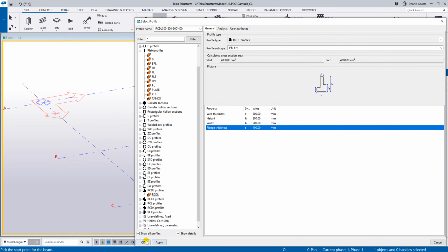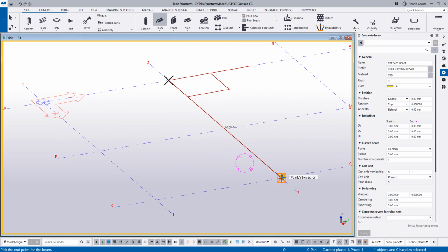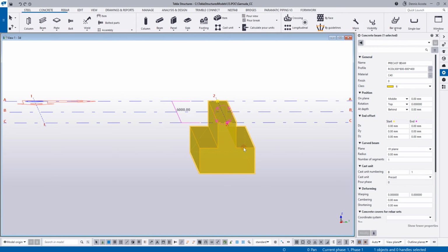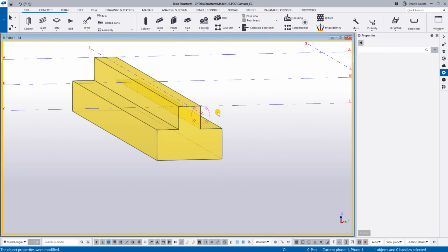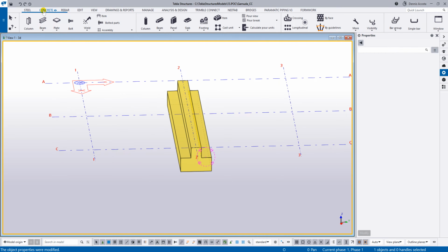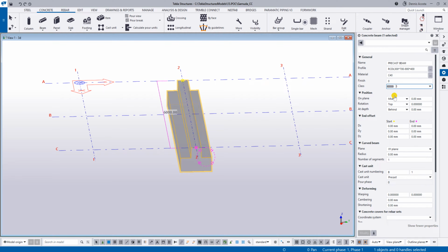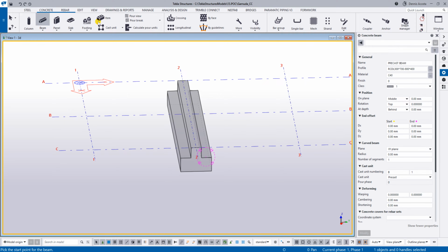Okay, apply, and okay. So look, if I have this one, this is my inverted T section. Or maybe we can change this one to 700, smaller, right? Now we have a beam. We can add now the beam. Let's say, maybe I'll change this one to color one. So maybe we'll add a beam here. The precast beam could be 600 by 450, and then pick this one.